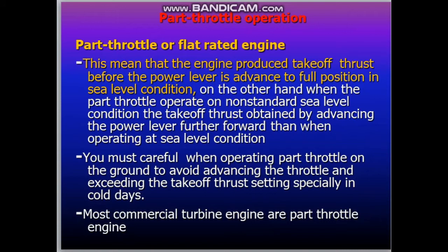Part throttle or flat rated engine. This means that the engine produces takeoff thrust before the power lever is advanced to full position in sea level condition. So this type of engine will produce thrust that allows for takeoff before the lever, or the throttle, arrives at the full position. That's the meaning of part throttle.